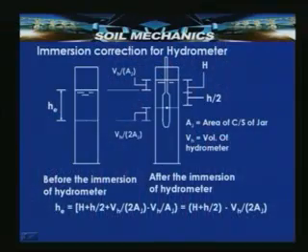Let us consider a jar with a suspension. Then if you see here, this may be the reference depth, which is He, and He here is determined after elapsing time Td. We can say that the increase in the height of the suspension is Vh by Aj, and at the center of the hydrometer, it is Vh by 2Aj.